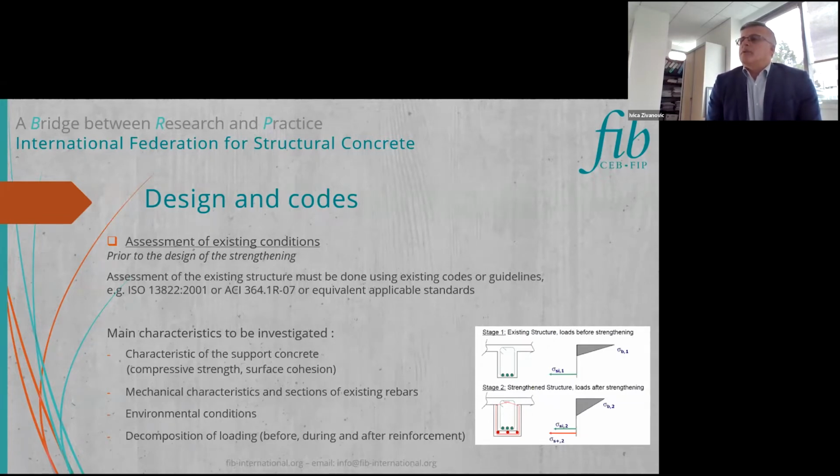The main characteristics to be investigated are, of course, the characteristics of the substrate or concrete support in compressive strength, in surface cohesion, the mechanical characteristics and sections of existing rebars, the environmental condition of the structure, and the load cases, of course, before, during the operation and after the reinforcement.